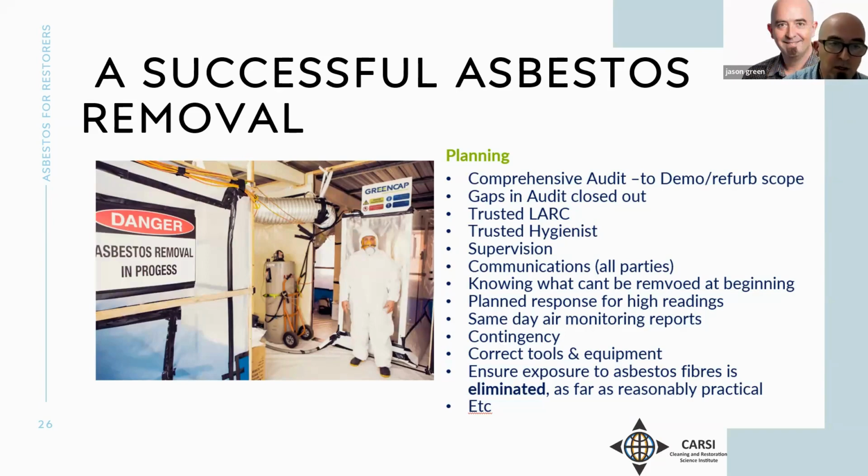It might be a mold situation and you're going in there removing ceilings or whatever. So if you don't know what's behind that, then you really need to take precautions proactively to ensure that you're protected. So using a trusted licensed asbestos removal contractor. Obviously you want to use the proper licensed removal contractor. If it's basic bonded materials, then your bonded class B license is more than adequate.